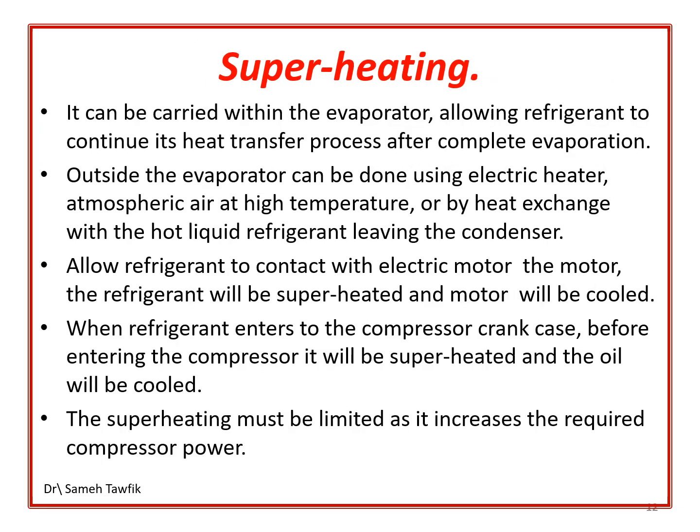Superheating. It can be carried out within the evaporator, allowing refrigerant to continue its heat transfer process after complete evaporation. Outside the evaporator, it can be done using an electric heater, atmospheric air at high temperature, or by heat exchange with the hot liquid refrigerant leaving the condenser. Allow refrigerant to contact the electric motor. The refrigerant will be superheated and the motor will be cooled. When refrigerant enters the compressor crankcase, before entering the compressor it will be superheated and the oil will be cooled. The superheating must be limited as it increases the required compressor power.